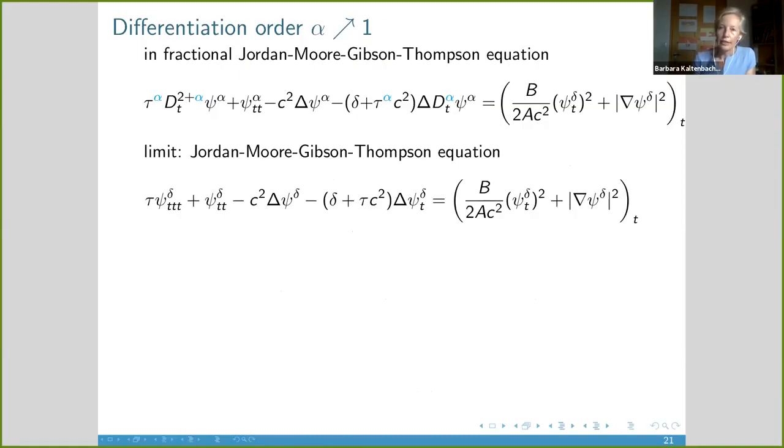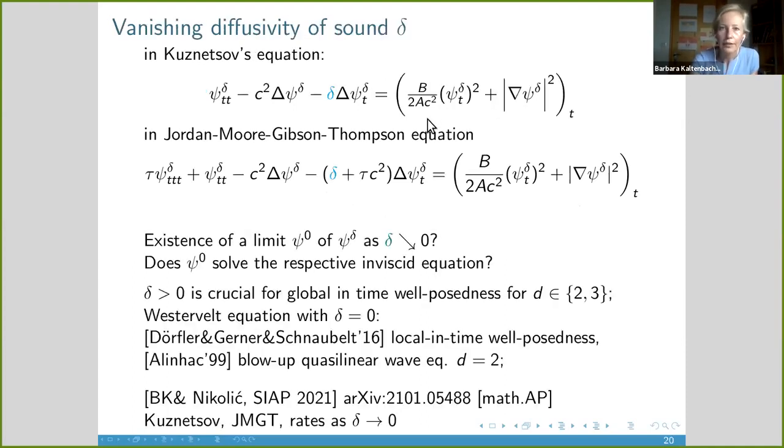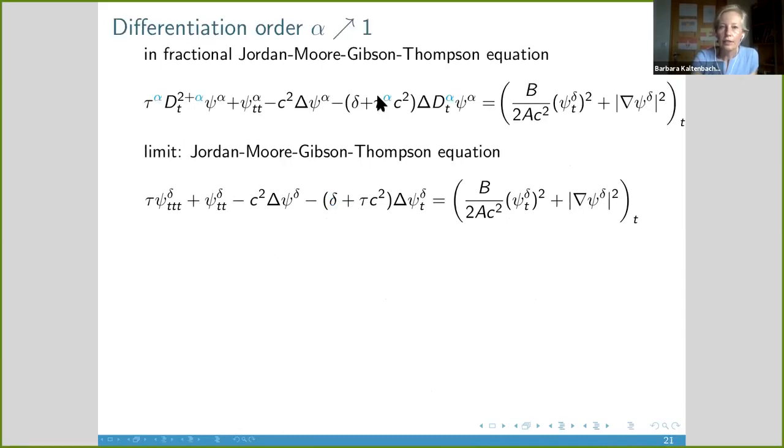So if one looks at the behavior in the frequency domain, then one has frequency dependent damping. And this is not just linear with frequency as it would be for this damping term, but it goes with a certain power law that one can extract from measurements. And so people have been looking at these fractional order equations in acoustics for several years by now.